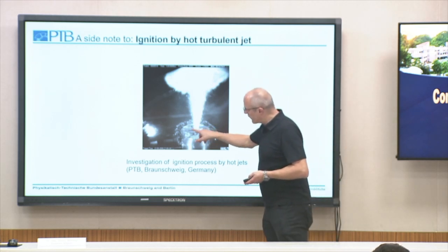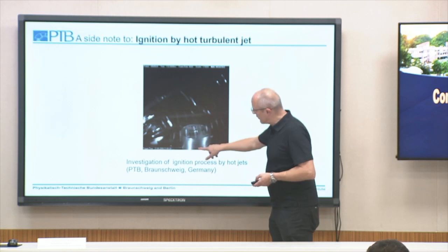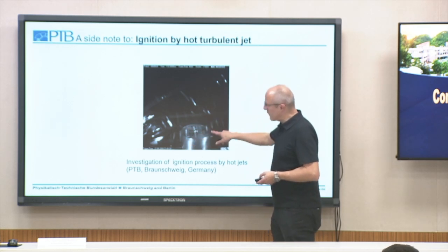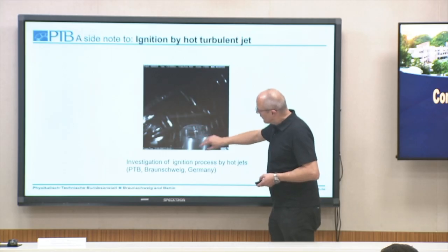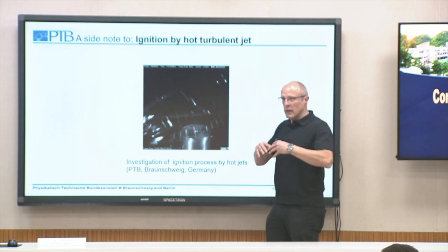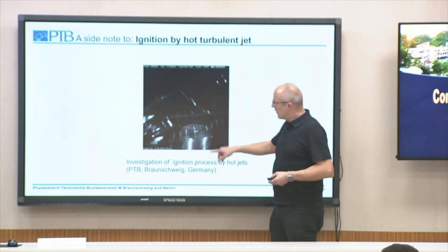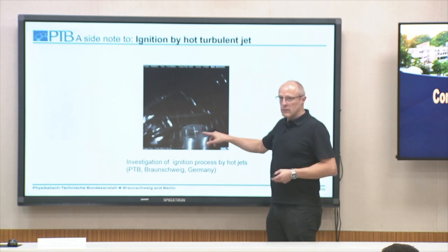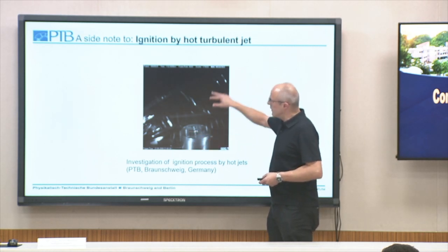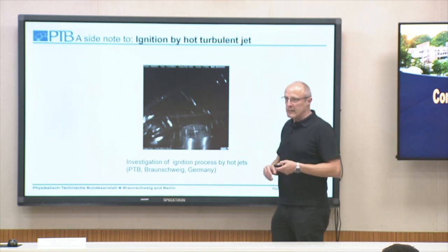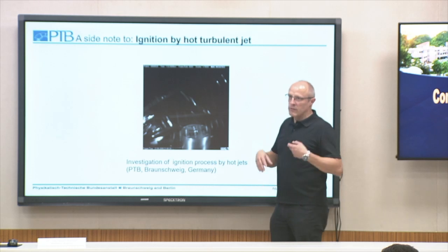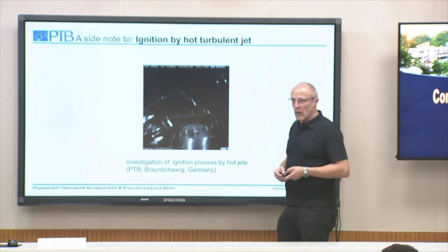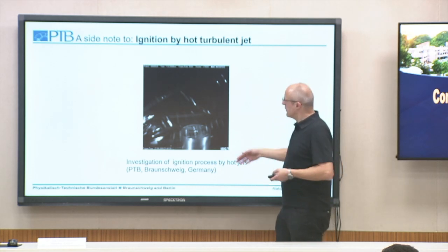And here we see this again. Here we have a chamber where the ignition with a spark occurs. And here we see a nozzle or an opening. Here combustion takes place, and pressure is increasing. Finally, the flame reaches this nozzle, and there is of course a pressure difference between inside and outside. So we have a fast acceleration of the flame, a very fast outflow up to the sound velocity of the hot gas, so up to maybe 2000 meters per second.